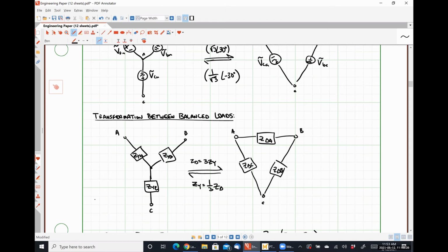It's purely resistive, so the math is rather trivial, but it is technically unbalanced. In that particular question, it's a Y-connected source to a Y-connected load, so there's no need to do a transformation to begin with. You just have to brute force the analysis.